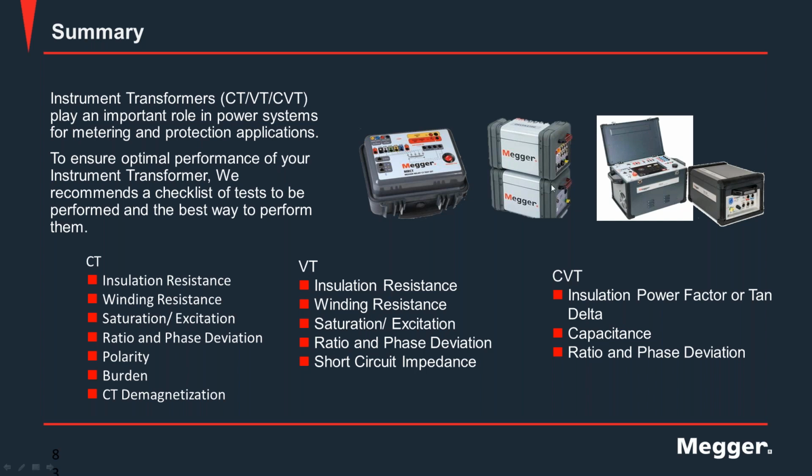And if you want to do CVT testing, I can recommend these two, the Trax and the Delta 4000, wherein you can achieve the 12 kV injection. Of course, you need to remember that you need the reference capacitor, the 10 nanofarad capacitor.